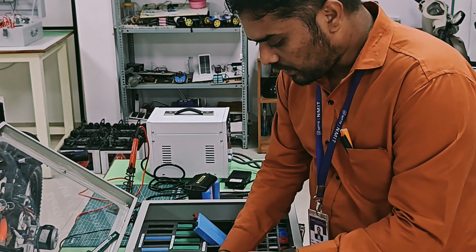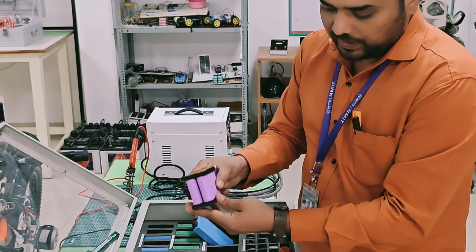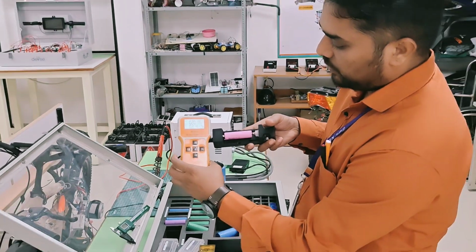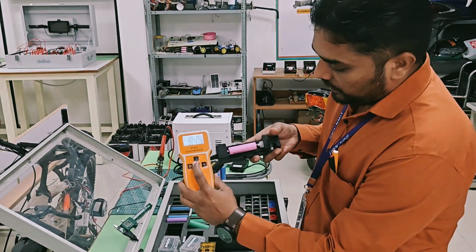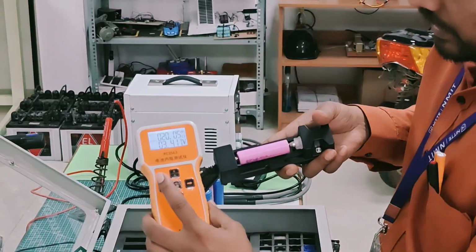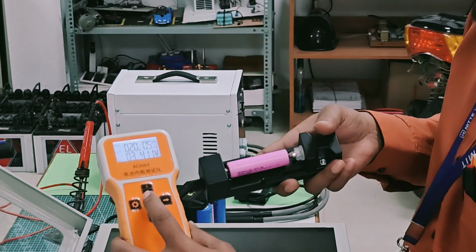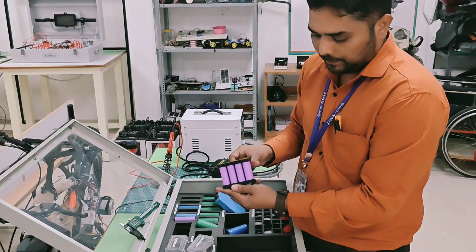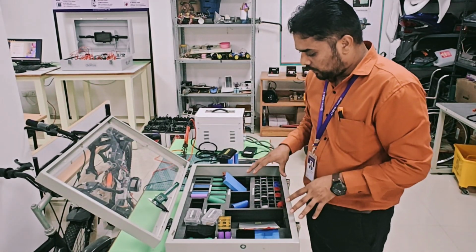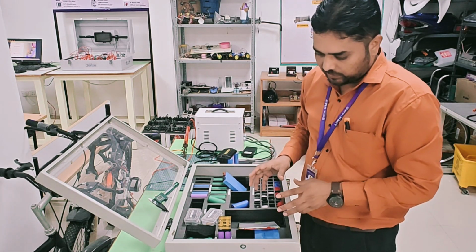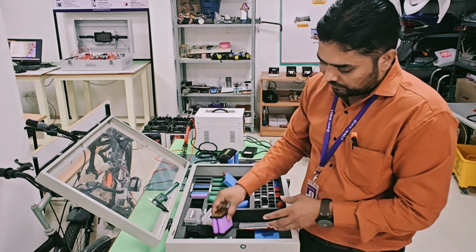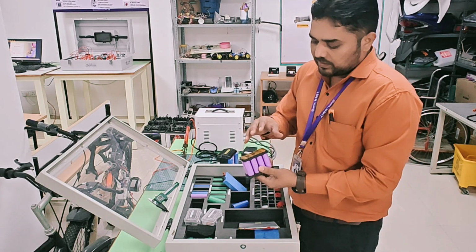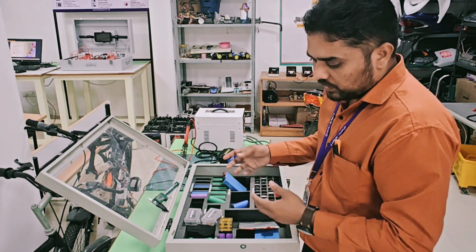Before constructing this battery pack, first I need to measure the internal resistance of each cell with this IR tester. If it is more than the prescribed value, then I am going to discard that cell. If within the limit, then I am going to use it in the construction of the battery pack. Fine. So this is about cells depending upon form factor, and how the battery pack is constructed depending upon the requirement, in series and parallel combination. Then, how is the cell discharged?